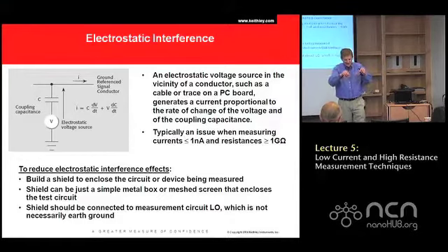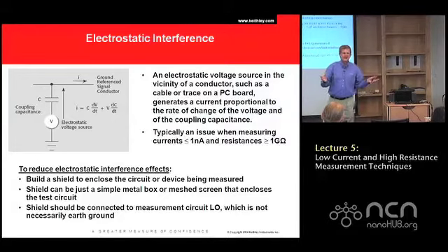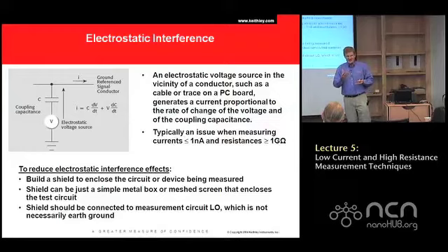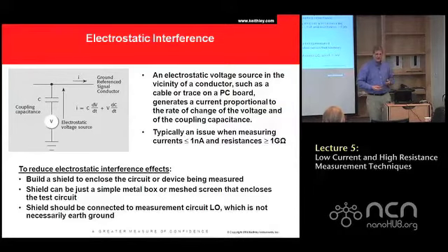And we'd hook everything up, we'd set the probes down, we'd close the lid, and then we'd come over to the instrument and we'd make the measurement. And that whole light-tight enclosure was our electrostatic shield. I can't tell you how many times I've seen electrostatic shields, light-tight enclosures, not connected to the instrument. It was just sitting there floating in space. It could go anywhere it wanted to go. So you have to make sure your electrostatic shield is connected to the common of the instrument.